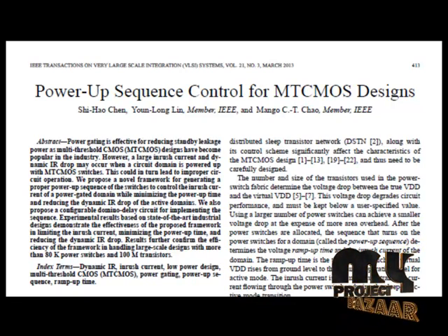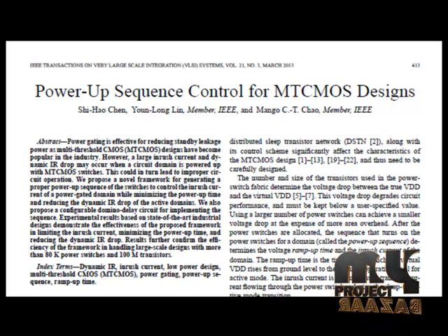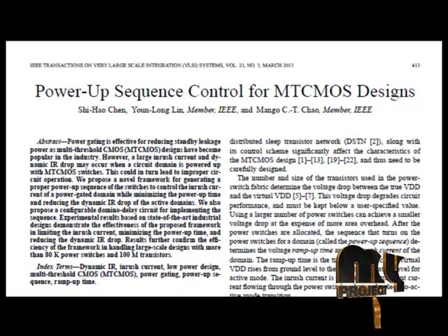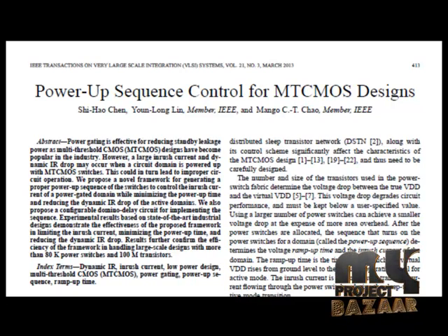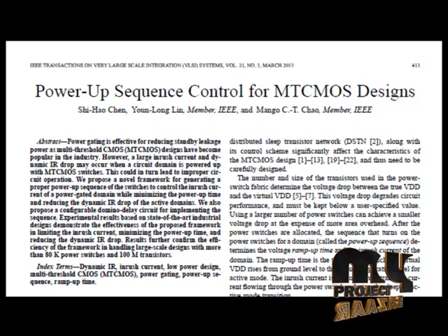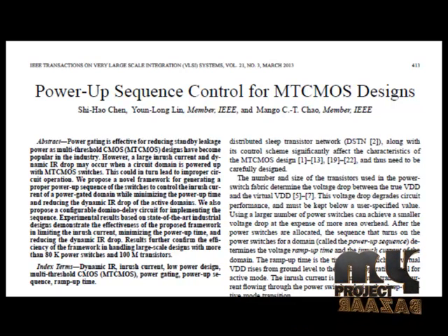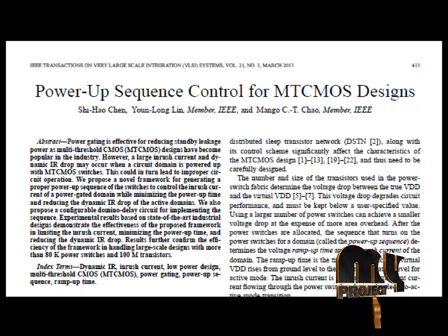Synchronous circuits cannot take full advantage of such an aggressive power gating control scheme, as local supply voltages must reach nominal values to prevent the synchronous circuit from violating its timing requirements, for example, setup or hold constraints of state holding elements.